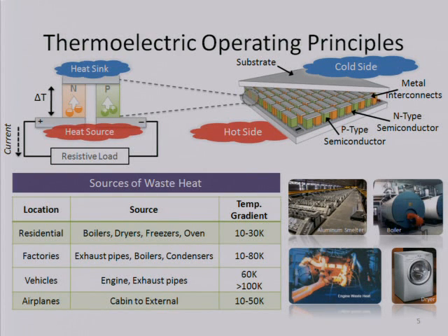And lo and behold, you can generate electricity which can flow through some sort of a load on the outside here. This is what a practical thermoelectric generator looks like. You can buy these things these days. There's a bunch of PN elements in it which are connected in series, and the heat flow is in parallel from the hot side of this device to the cold side of this device.